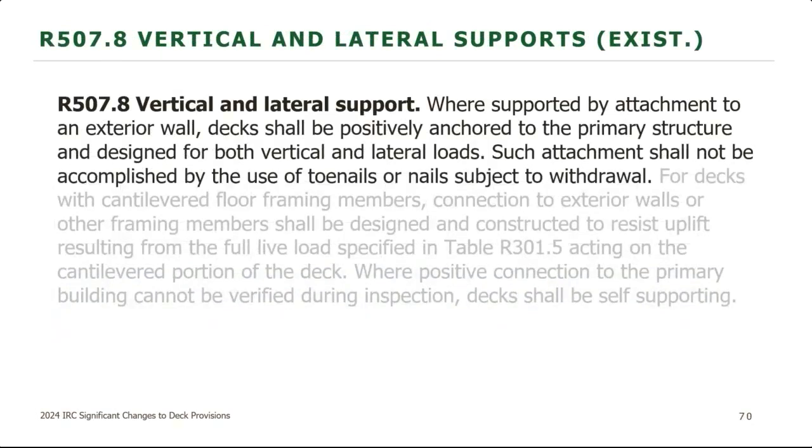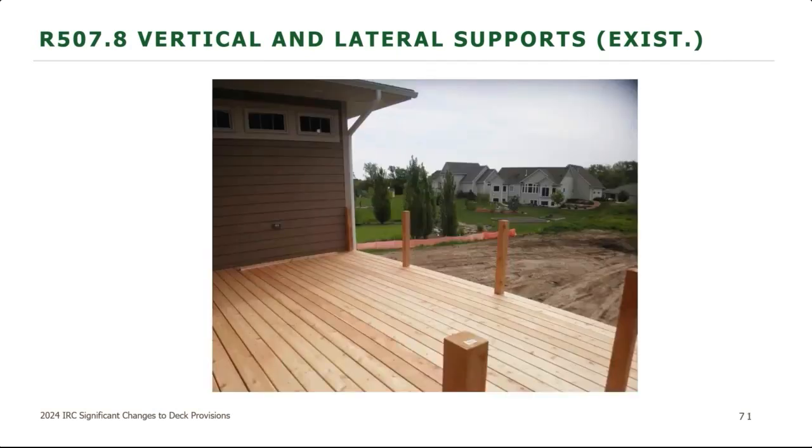Vertical and lateral support is required. Decks supported by attachment to an existing wall: the deck shall be positively anchored to the structure to support both vertical and lateral loads. We talked about those earlier on. And then here's just a typical deck.